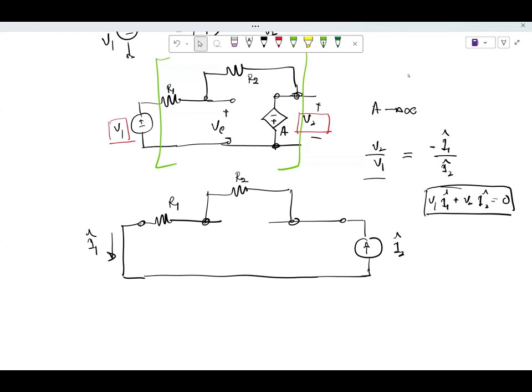And number two, we go inside the network and we see that we have this voltage controlled voltage source. Now that also needs to be replaced. What should we replace it by? This is easy. We should replace it by a current controlled current source. So the controlling terminal is here. Let's say I call this IA, and this will be the current controlled source of value A times IA, going up, right? Because this is simpler to remember.